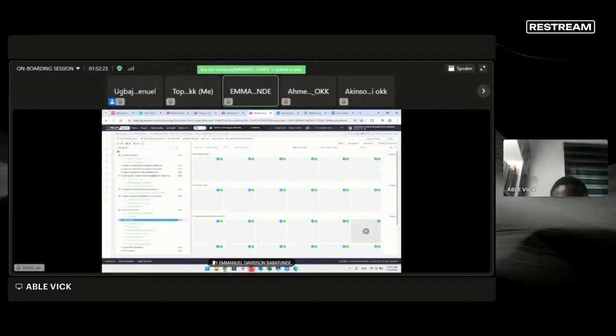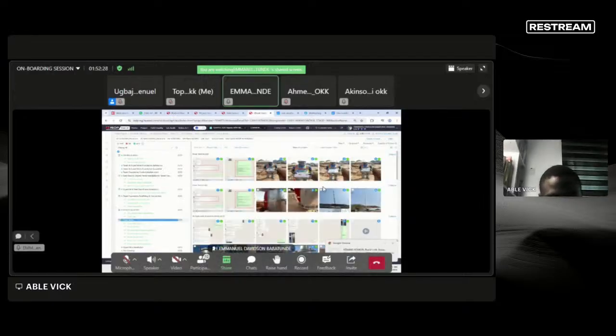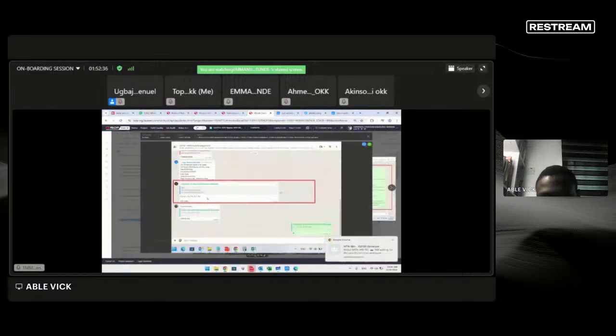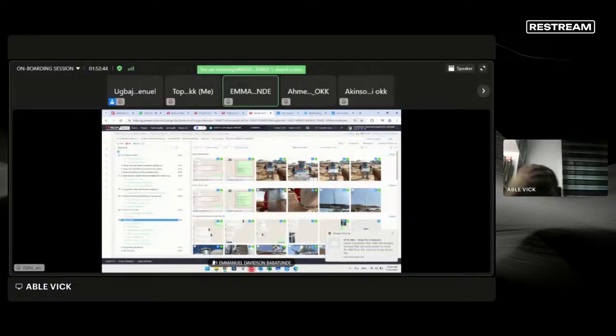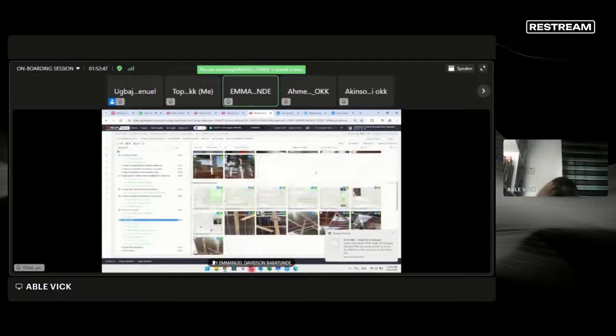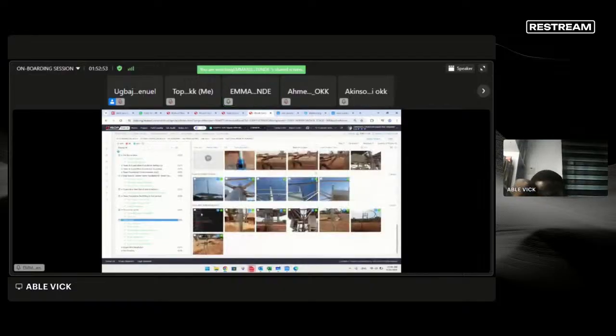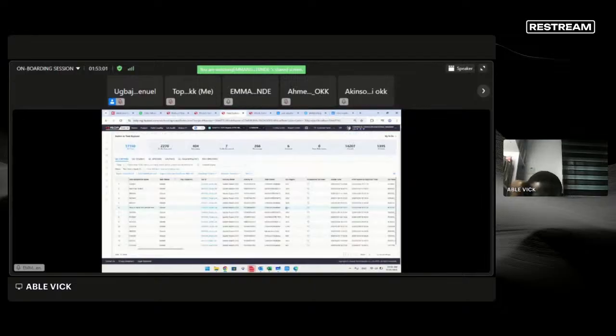For the tower erection, before you install your first leg, you need to check the base plate, check the foundation base plate again and confirm its level before landing your first leg.